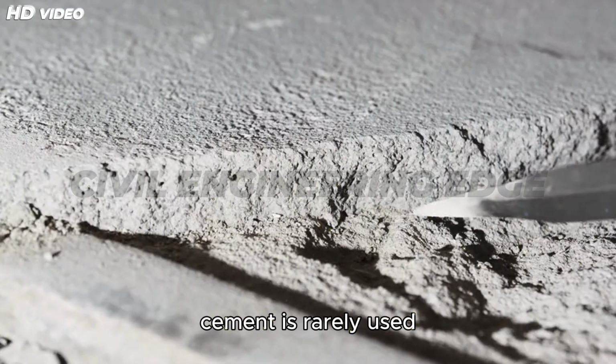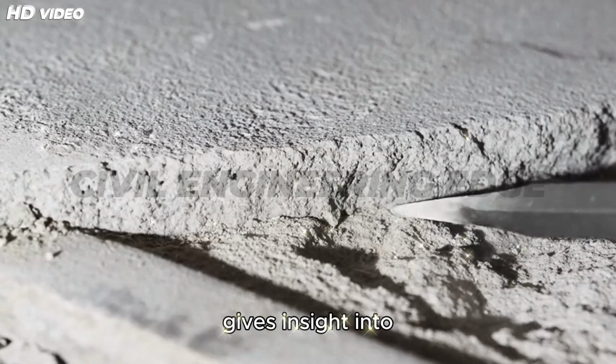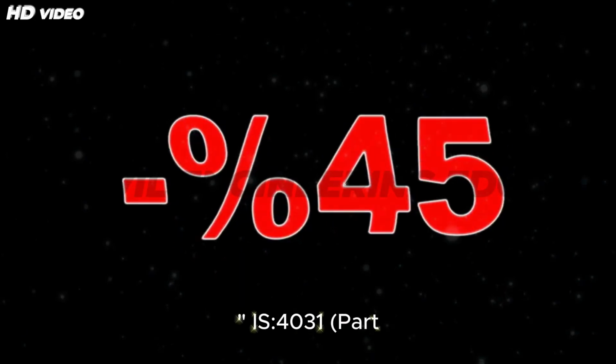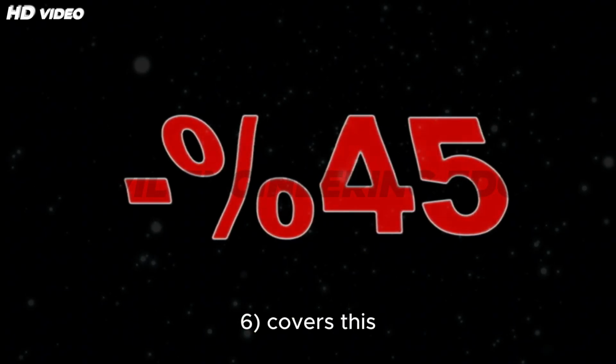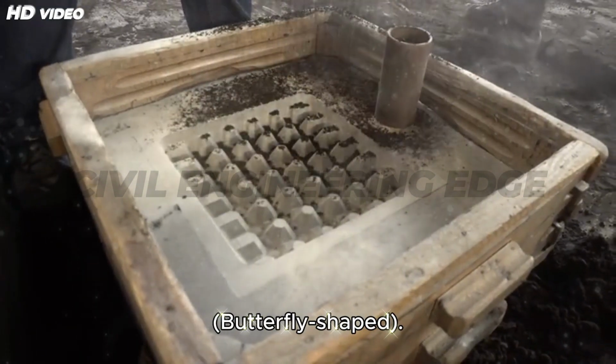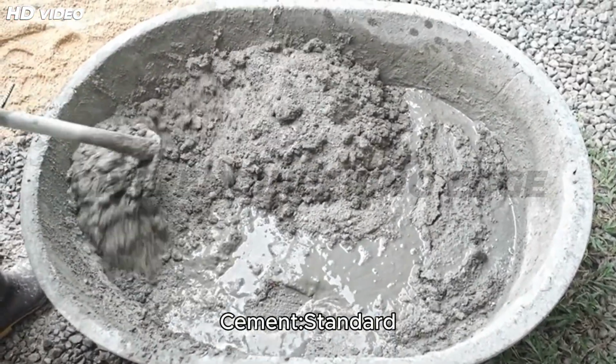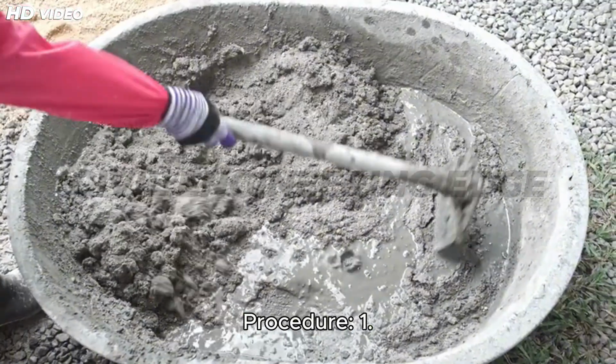Tensile strength of cement. Though cement is rarely used alone in tension, its tensile strength gives insight into its binding capability. IS 4031 Part 6 covers this test. We use the butterfly-shaped briquette mold. Standard ratio, cement to standard sand equals 1 to 3.